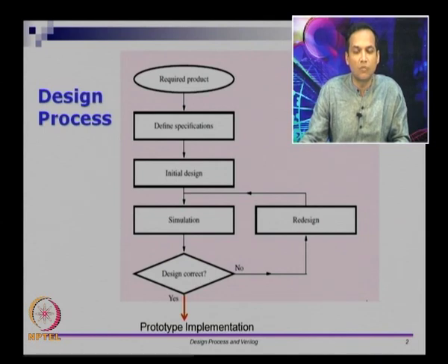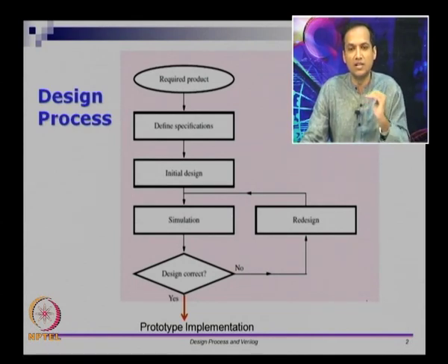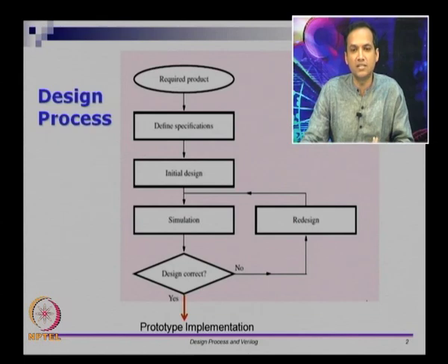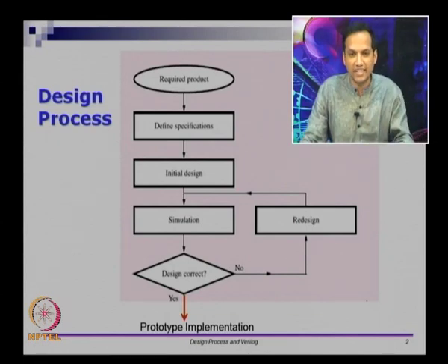What we are going to do in this course is learn how to do initial design using a language called Verilog. I already mentioned this in week 1. Verilog is a hardware description language. We are going to do our design in Verilog, and this Verilog design will be a text based description that a computer can process. With appropriate tools, you can take this Verilog design written as a piece of text, give inputs to it, and find out what the outputs will be. You can keep doing this till you are comfortable with the fact that the design is correct.